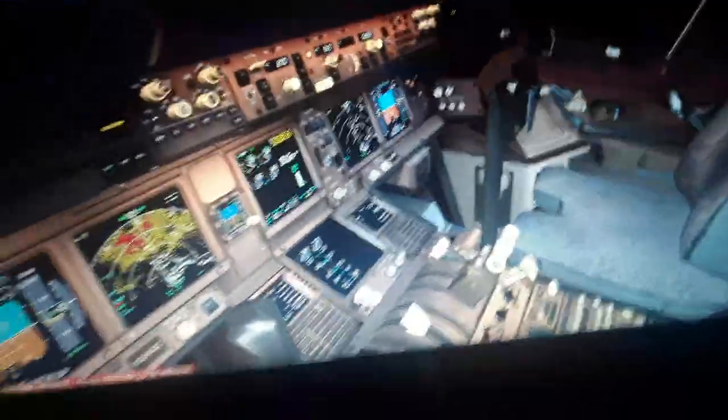So the autopilot and flight director system, as I told you, commands the thrust and the airspeed guidance. So we select an airspeed, also in nautical miles. We select the modes, the flight level change, the airspeed, the auto throttle with the speed, and the climb continues. So the navigation with this command, the engine thrust rating, like the N1, or the engine power rating. From takeoff, climb, cruise, descent, and approach and landing, we have the engine thrust commanded automatically, depending on the configuration of the aircraft in flight and the altitude of the aircraft in flight.